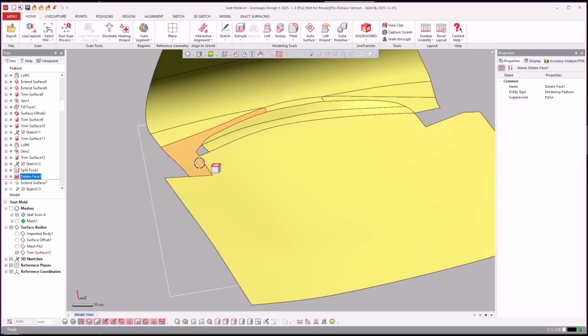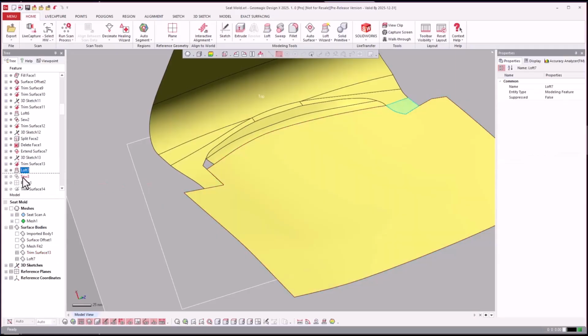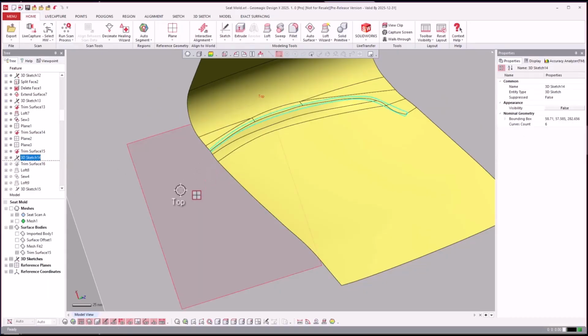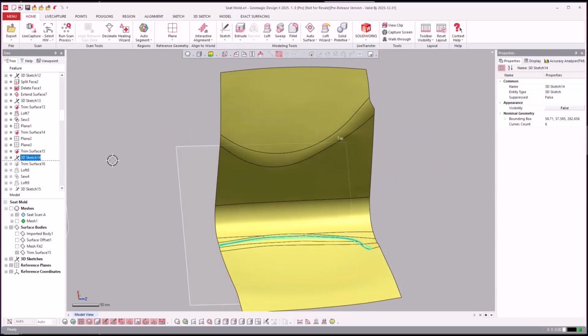And they're going to probably do that same thing over here as well. And then extend. Trim with that sketch that they drew, and then loft between the sides, the edges. That way we have a nice curvature to that boundary, and then sew it all together to make it all one surface. And then do the same thing on this side. So you see here that they're, oh, never mind. I jumped forward a few steps. It looks like they're going to, let's just jump back here.